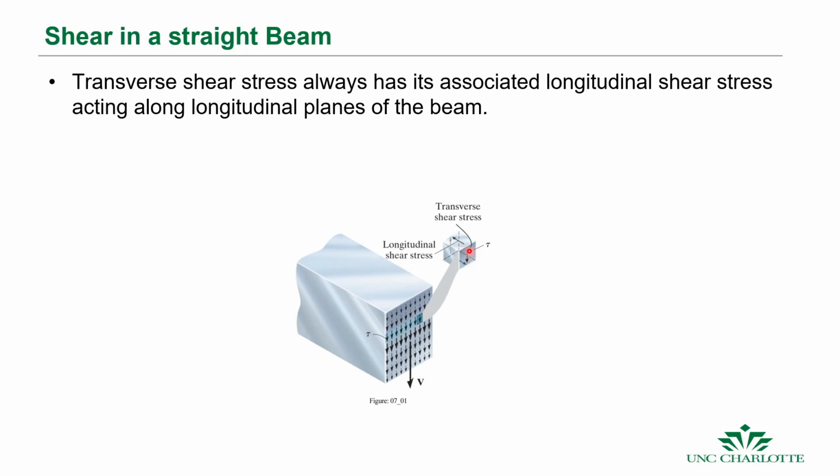Another way to think of it is you try to pull this material down and out of the beam. It's going to have this resistance to pulling at the top surface. However you want to think about it, you can think of it in terms of the balance of forces here. If you take those forces across the center of this cube, it would cause it to rotate and spin, because it's a couple. It can't do that, so it has to have a resisting moment. The resisting couple or moment is provided by the material above and the material below. So that's how we get those shapes. This should all be a review to you.